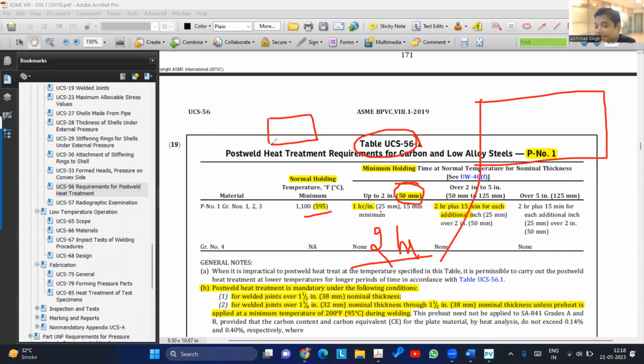Okay, now let us consider that the job we welded. Okay, we did the post-weld heat treatment by using this cycle. Now this cycle of 2 hours, I can even achieve in 1 hour, one go, and then again 1 hour in the second cycle. That is also possible. Cumulative should be 2 hours. So in one go, I did the post-weld heat treatment of 2 hours. Okay. After that, there was a requirement of radiography. I did radiography. I got a repair.